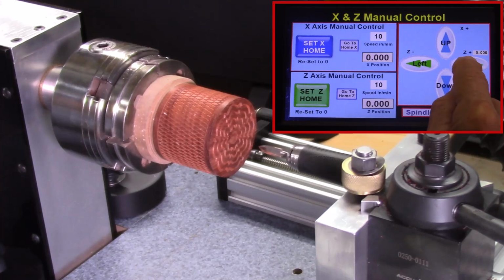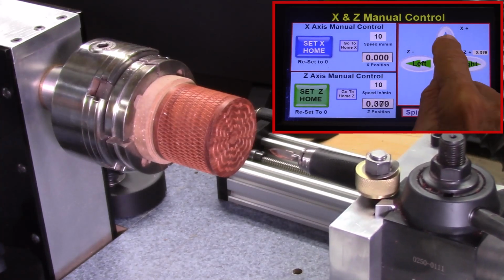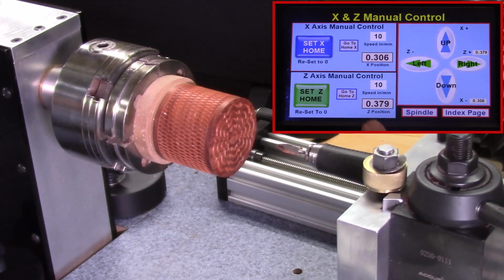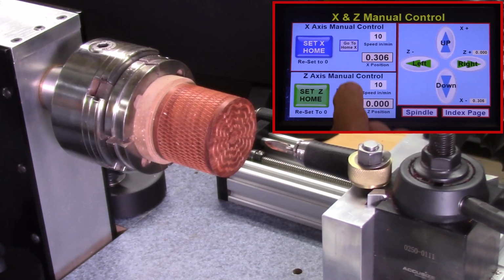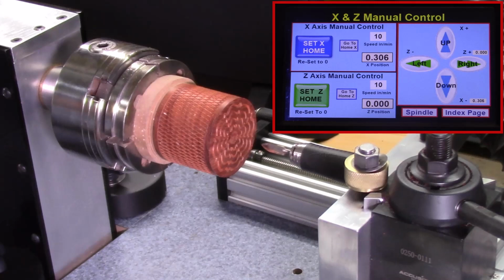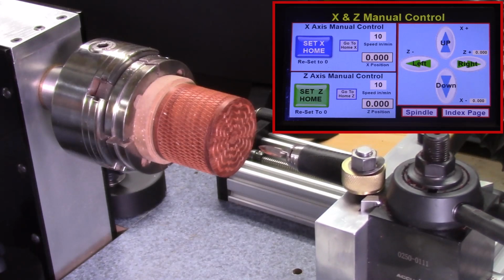For example, let me move it away, both directions, and you see the numbers have changed here. Now if I say go to home, it goes to home, changes it to 0, do the same thing in the X direction, and it's back to home. So this program is used a lot in other programs where I want to set my home position. I usually want to set my tool in a certain position right against my board as a starting point, and then I'll set my home position there, and then go back to the other program to start the operation. But this homing position is quite useful.